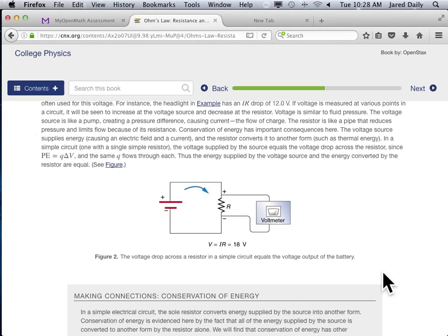For example, you can measure resistance. You can measure even capacitance. You can measure all kinds of things, but the downside is if you forget which one you're using and hook it up like it's a voltmeter, but it's actually working like an ammeter, then you're in trouble because you'll drive a lot of current through it and burn it out. So that's where the danger comes in.